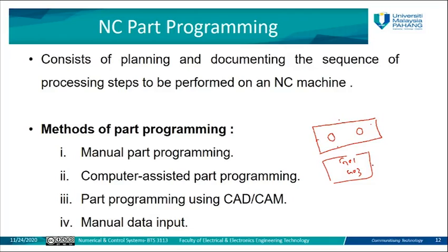Then this code, or this computer with the software, will be connected to the MCU, the machine control unit, and it will send the program into the MCU. This is one of the most common approaches for modern CNC machines. The designer does not need two steps, one to make the design and the other to write the program. After you complete the design, the computer itself will generate the code for you. This code will be fed to the machine, and the machine will perform the required task. Okay.